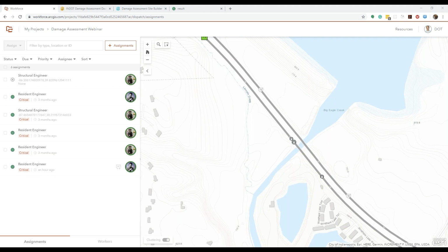in terms of the precision of the device, we're dependent on whatever the device is capable of providing. So if I'm out in the field with a cell phone and I don't have any additional GPS devices with it, I'm going to get what a typical cell phone can carry, which is right around 3 meters, 15 feet. Then you can improve that by adding on GPS devices that have higher capability. I know there are a couple of models out there that get you in the 9 feet range and 8 feet range, and then you can progressively get even better by going into high precision devices, which can improve the precision even more.